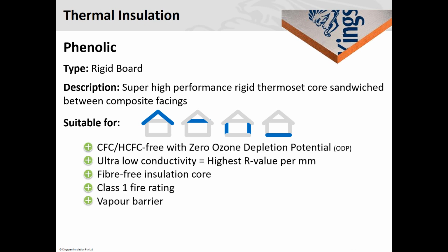As far as in the floor, if it's suspended, yeah. But that being said, we also use it underneath concrete slab on ground as well, because everyone walks on concrete. It's bloody cold. So if you have underfloor heating in your concrete, there's a requirement to have an insulation value of at least 1.25. That would be our 25 mil thick Kooltherm.